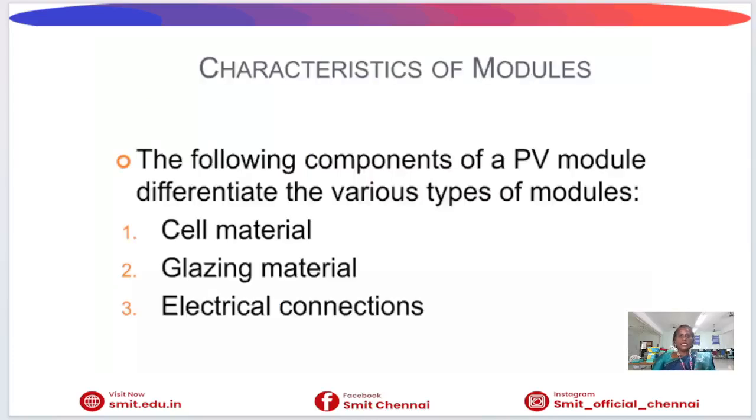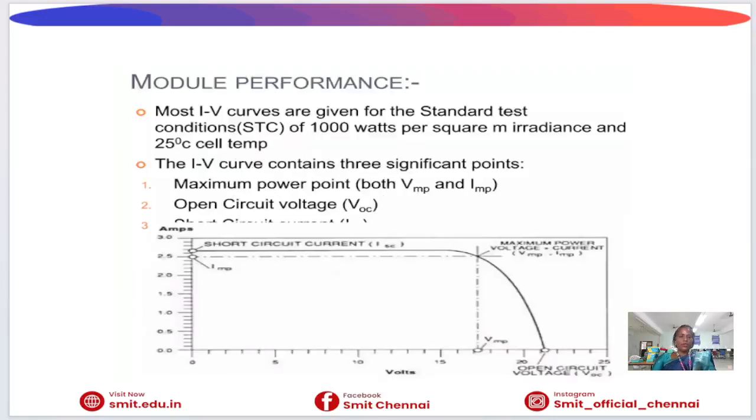When sunlight strikes the solar cell, photons transfer energy to electrons present in the semiconductor material. These electrons gain sufficient energy and become free from their atomic bonds. The electric field present at the PN junction drives these free electrons toward the N side and holes toward the P side. This separation of charge carriers prevents recombination and enables the generation of electrical energy.